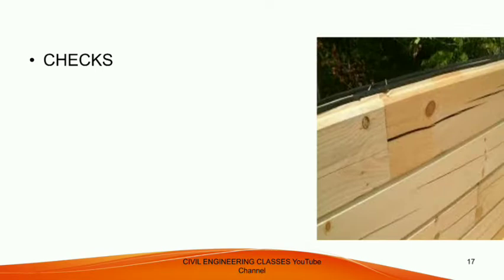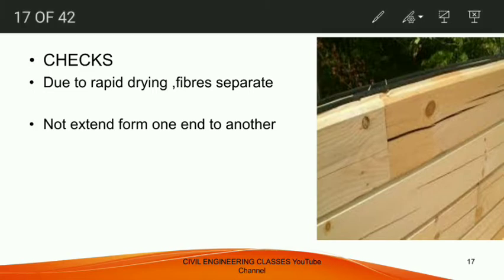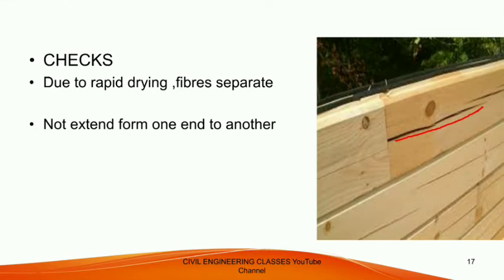Next one is check. Due to rapid drying, there will be separation of the fibers. But this separation does not extend from one end to another. It will end something like this. It won't extend over the whole section. This is called a check.